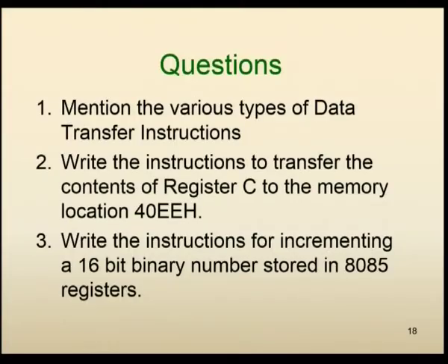Now, I will give a few questions for you to find the answers. Question number 1: mention the various types of data transfer instructions. Question number 2: write the instructions to transfer the contents of register C to the memory location 40EEH. Question number 3: write the instructions for incrementing a 16-bit binary number stored in 8085 registers.